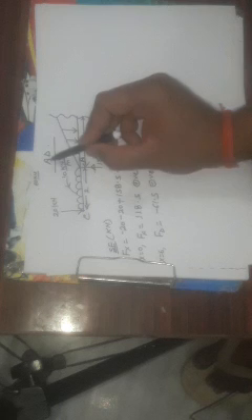Now what we are finding: at point A, the value of shear force is positive, and at point D, the value of shear force is negative, right? That suggests the variation changes its sign in between this portion. For portion AD, the value of shear force at A is positive, and at point D it is negative. That means in between these two points, the shear force curve changes its sign. That means the value of shear force is 0 somewhere in between.